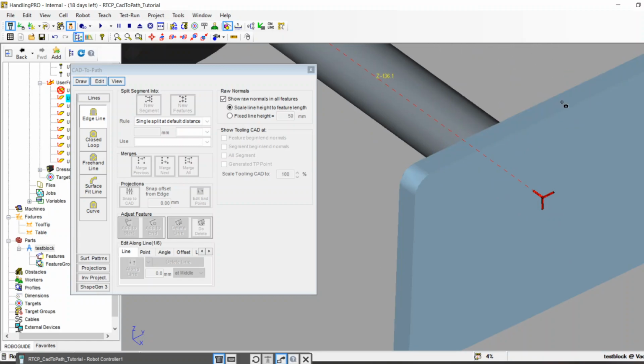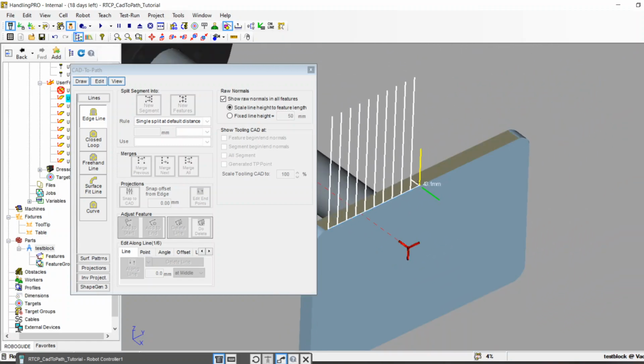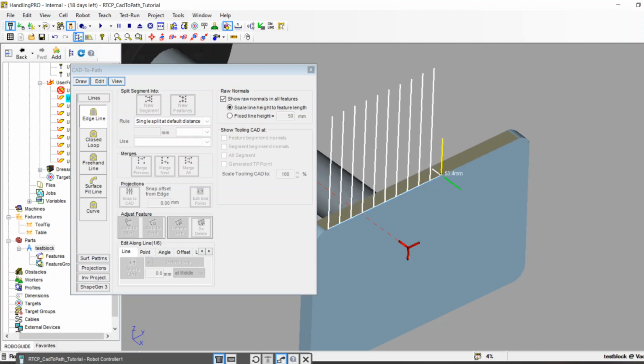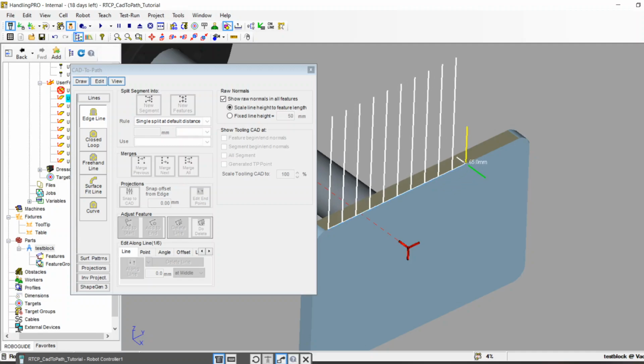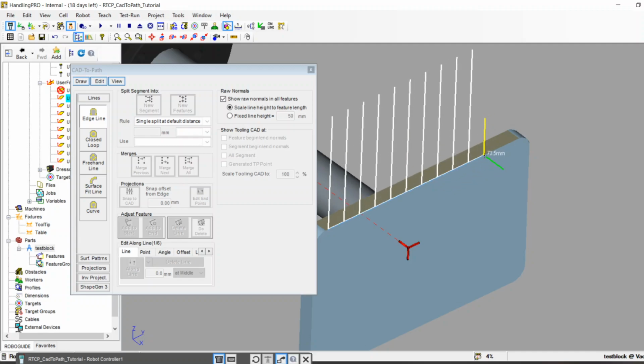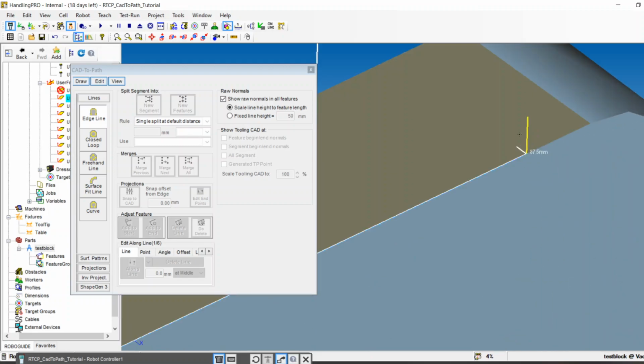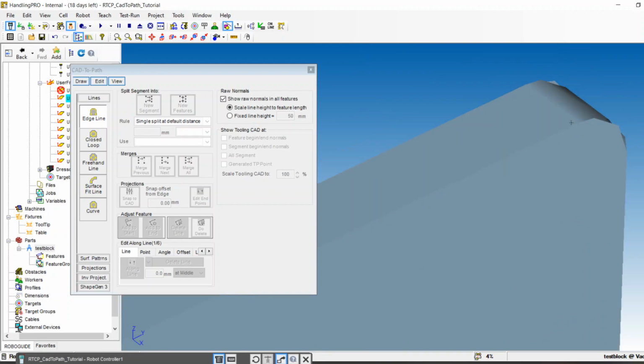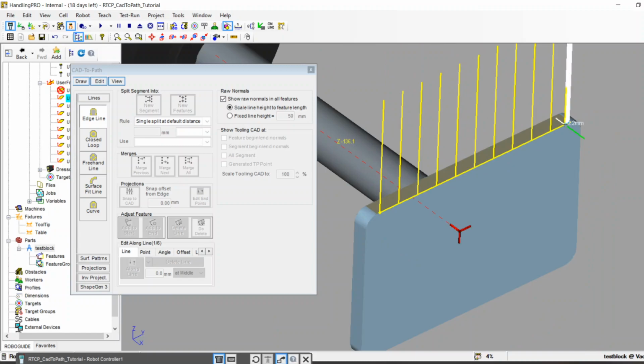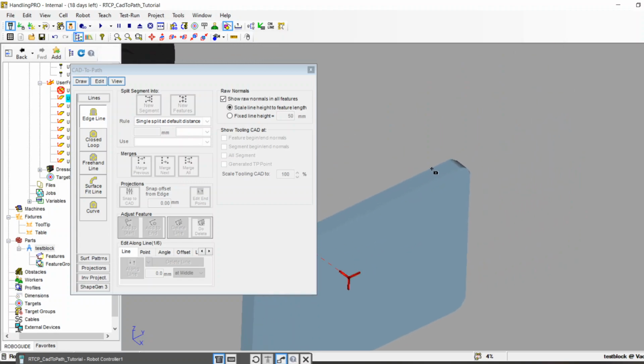That is a misconception. What I do care about is defining the normals everywhere that there can be a drastic feature change. So I'm going to move my mouse over to here, and I'm going to click. All right, so I clicked once at the beginning, once over here. You can see the normal vectors on the screen showing the path it's going to take.